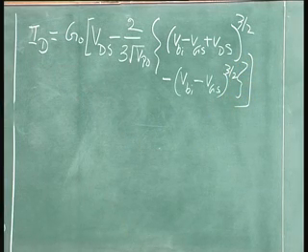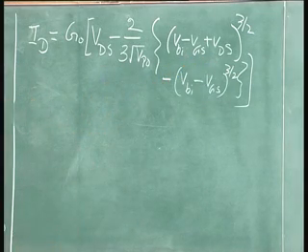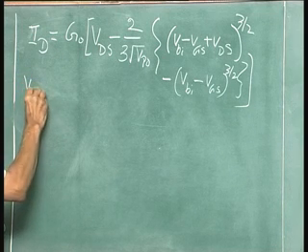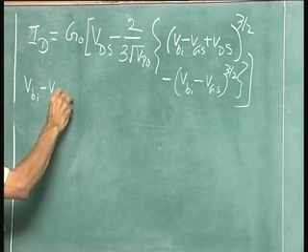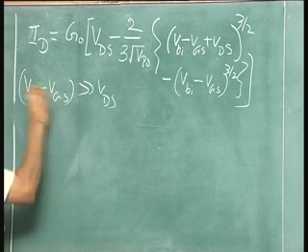That is what we have got. What we are trying to see is when V_ds is small compared to that, that is V_bi minus V_gs is much larger compared to V_ds. That is the case 1 that we are discussing.